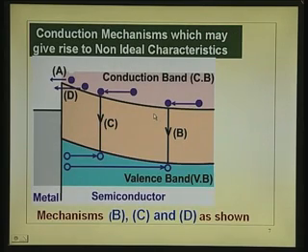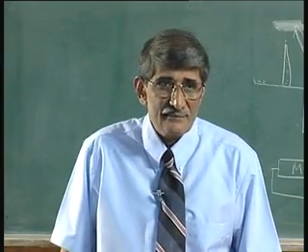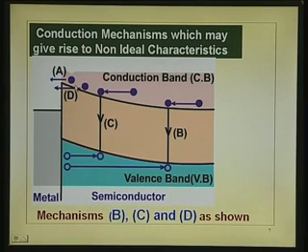I just put this diagram back, what you had seen earlier, to see what we are missing out here. We took into account in the current transport only this term, that is the electrons which are able to cross the barrier, the thermionic emission current as far as this side is concerned. Now, there are other currents which we have not taken into account. We will examine and see whether we really should worry about those. So, what are the other currents? One of them is this current, that is the hole injection and recombination in the neutral region.